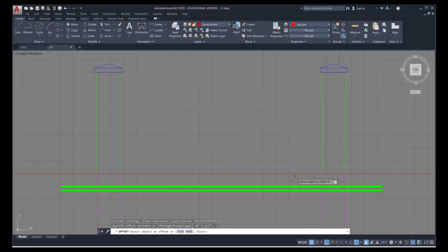It's a 1 inch base pipe, and then we have supports at 1'5", so offset 1'5". That one again is 1 inch, so offset 1. And the top one is 1'4" at the top of the arc, so offset 1'4", and then 1 inch again. So there's the general construction.